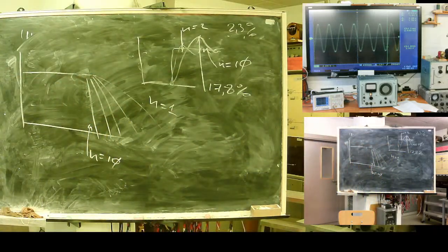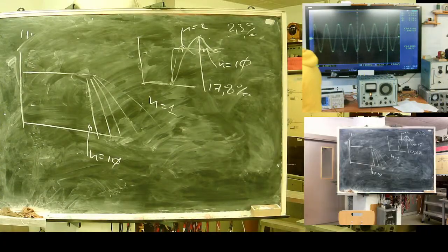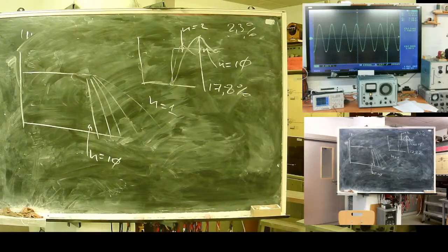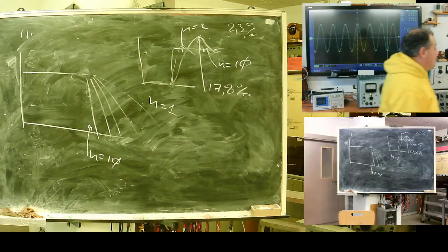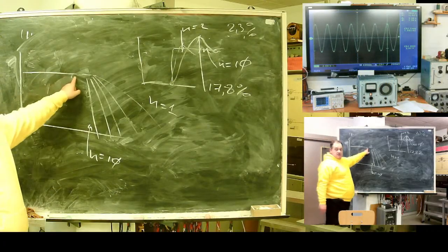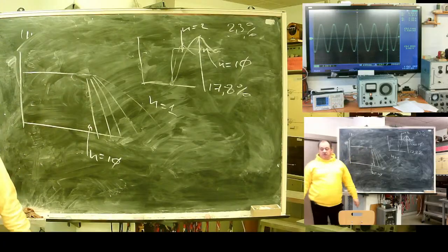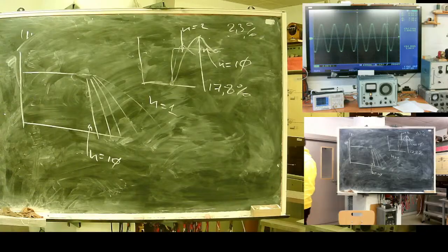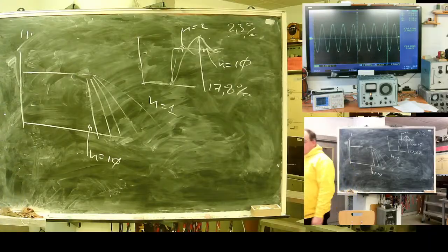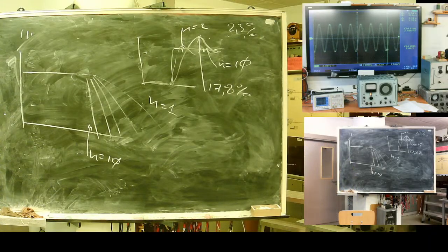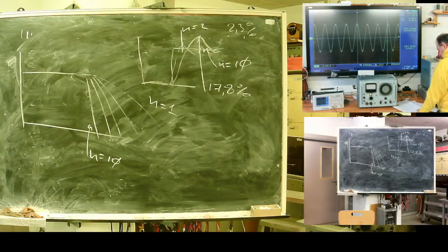But really, if you're looking for analog preprocessing with a straight, equal and nice line in all your operation frequency zone, you will choose Butterworth filters. In reality, there are plenty of filter design programs. You just ask for a Butterworth filter design and this thing will help you. You just set the knee point and order, and it will create it for you, because they are very popular in acoustic processing.